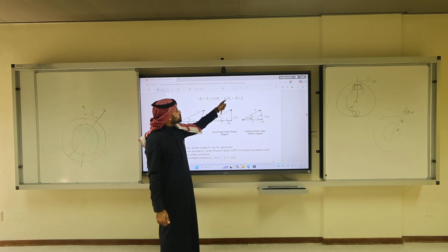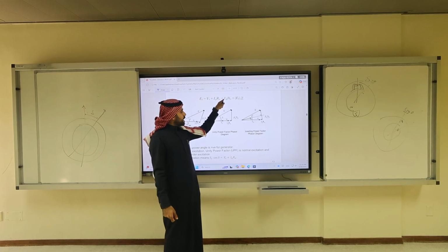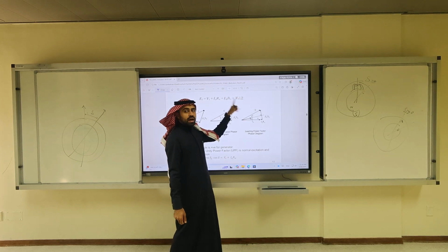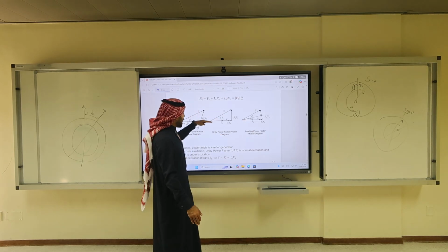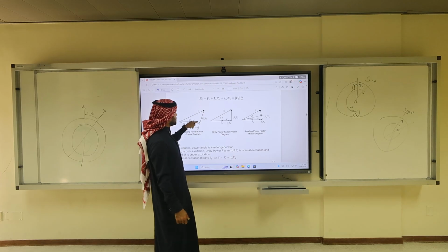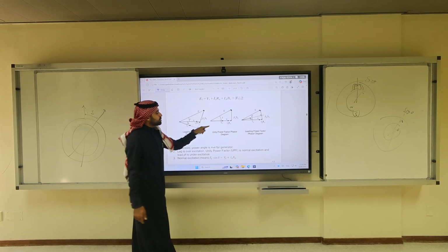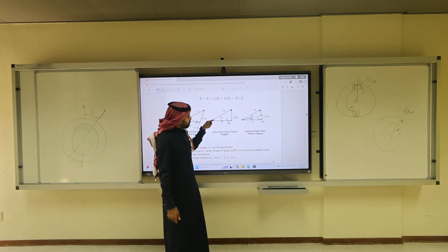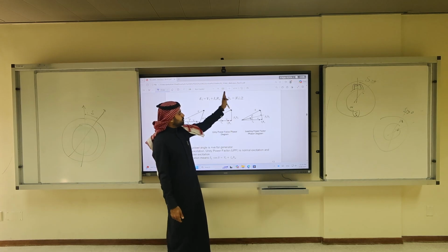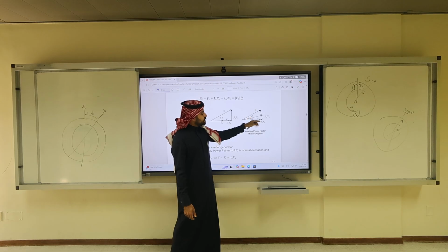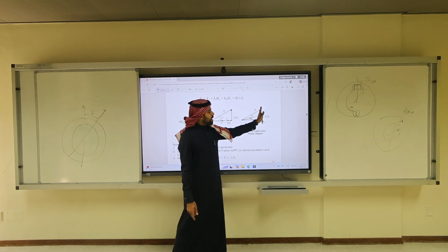The last quantity is j IAXS, which is 90 degrees. So scale IA with XS and add to the angle of IA another 90 degrees. So in this case, IA here, add 90 degrees, so it will be here. This is vector addition. For the unity power factor, IA is in phase with V, so the 90 degrees will be a right triangle. The last one, IA is leading, so j IA times XS will be a little bit more than 90 degrees.